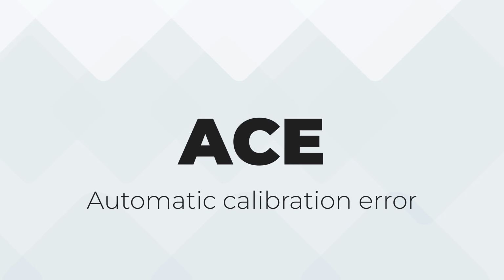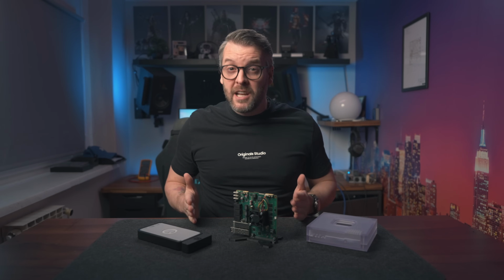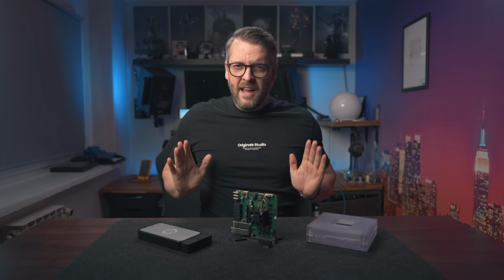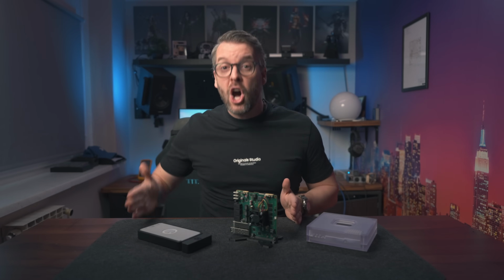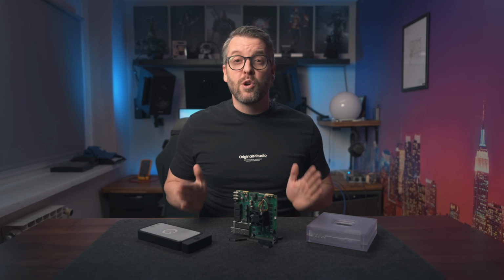ACE stands for Automatic Calibration Error, which means that the memory chips weren't able to properly calibrate themselves, which is part of a training routine that the DDR controller goes through on every boot. Now, to understand why this bit is important, let's look at what the process looks like if this bit is not set, meaning we have 100% perfectly configured and working DDR.